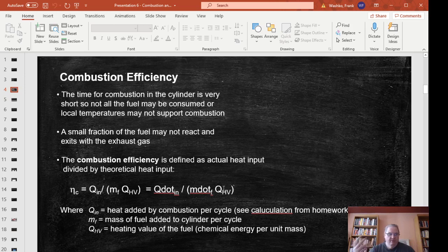A big part of the work there, especially as injectors came on, was that we wanted to see what the spray pattern looks like and how the spray pattern is affecting the burn rate, all these types of things. It turned into a big experimental area in the 1980s and 1990s, and continues on today. Trying to visualize, understand, simulate, and test how the combustion takes place in the chamber to get better combustion efficiency and more heat out of the fuel before we send it out the exhaust valve.